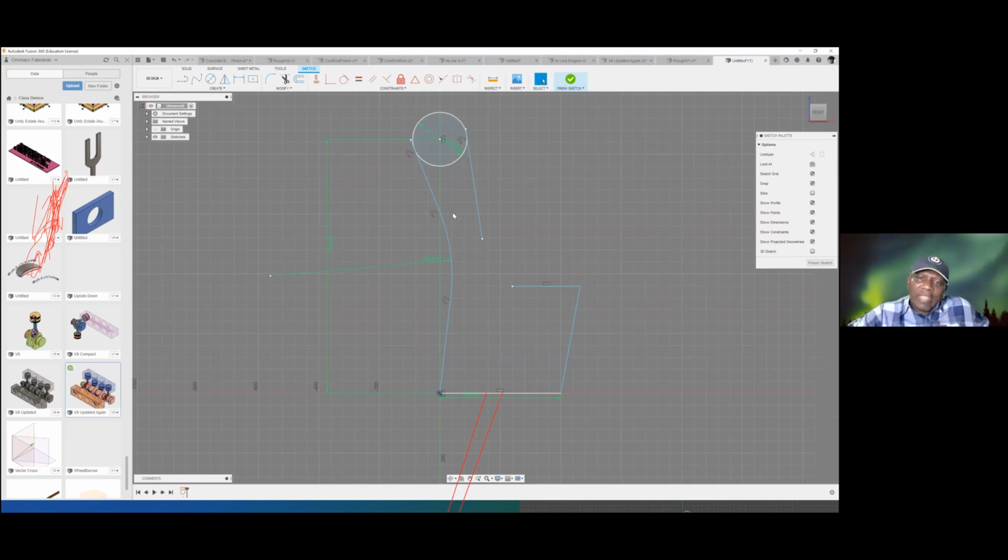Okay, the same way, I want this one and this one to be filleted to each other. So I pick the filleting tool. So this one and this one is the fillet. So again, I can make this the way I want it. Okay, so 138, let me make it 140 to make it a rounded figure.